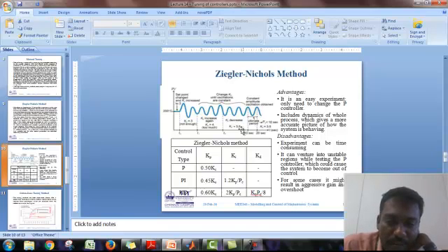In this graph, for critical value 3.5 you get a stable system, and one oscillation, that is the ultimate period, takes 10 seconds. If you apply these two values, you can find the remaining gains of the integral and derivative controllers. Once you find all the gains, you can feed them into the system and get a stable response as quickly as possible.